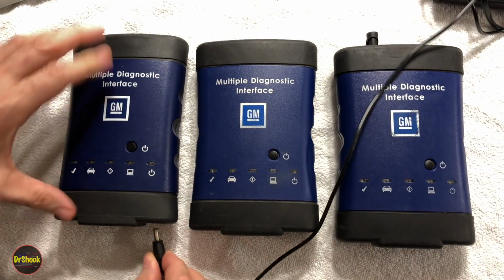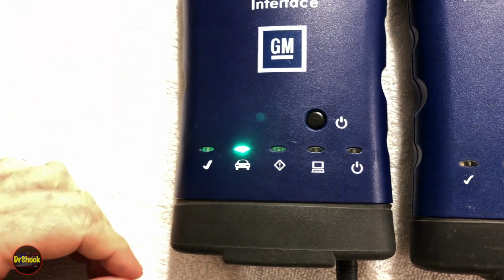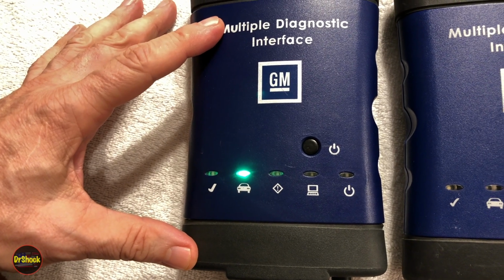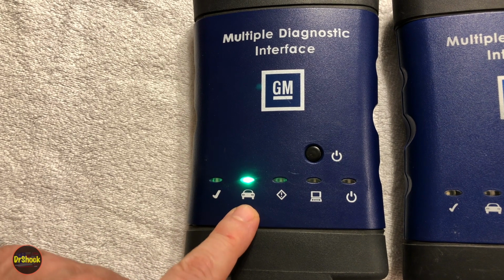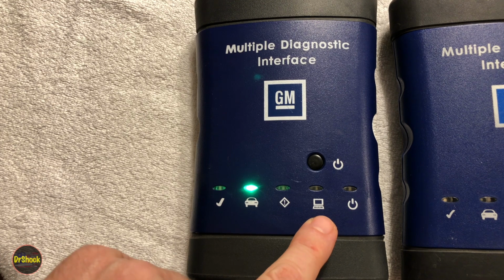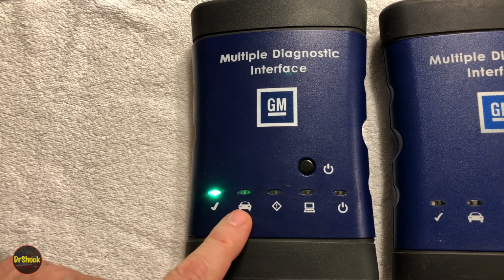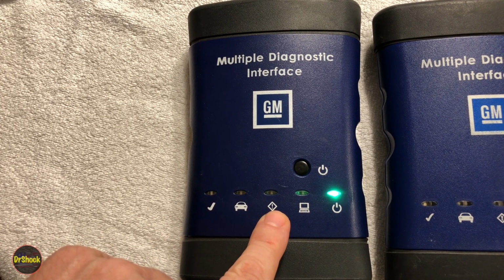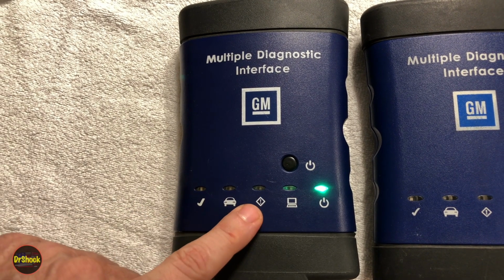Just going to power him up, and you can see during the power up he is going to error out with a particular failure case. Now this is a clone device, but this type of problem could happen on real ones too. So it stays at this first part of the POST for an extended amount of time. Normally this is a very quick check, and then it should move over here as part of the power-up test. But it's staying here for a long time, so it's having trouble, and then it jumps over here, and it jumps over here. And I don't know if you could hear that, but it has a couple of beeps, and then it goes over to power. So that's what's wrong with this one.